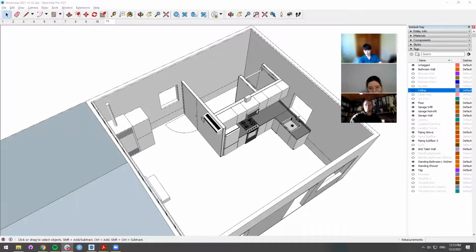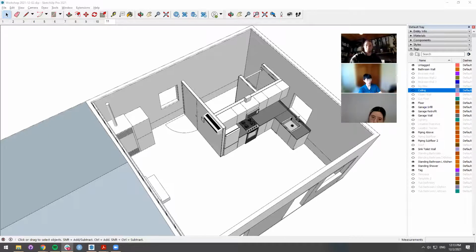Okay, I see one comment that came in the Zoom chat about lofts being considered double FAR, and Joe mentioned it depends on jurisdiction. I think that one way to think about this is that the average two-car garage is something like 400 square feet. So you're still under the JADU maximum size of 500 square feet if you were to bring in that loft space on a quarter of your area. And if you were designing this as an attached ADU, you might have a little bit more leeway because the size of that is dictated by 50% of the existing house or 800 square feet.